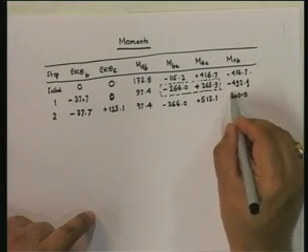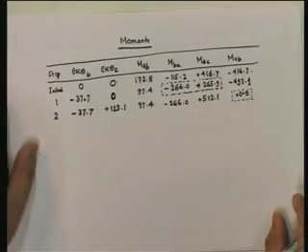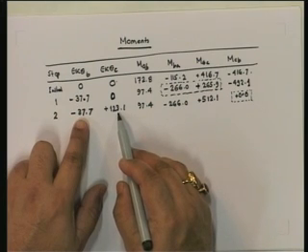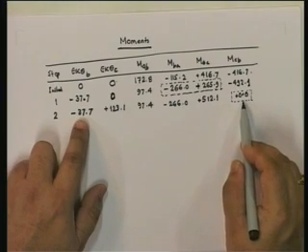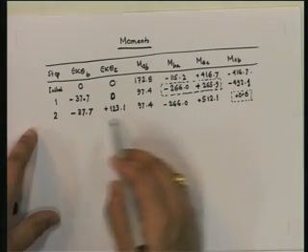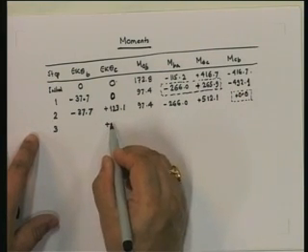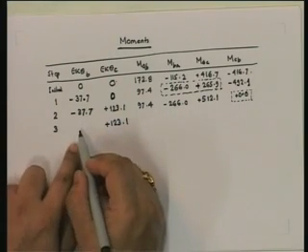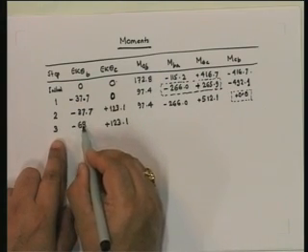What have I done? I have kept theta B and released theta C. As soon as I release theta C, what happens to MCB? It has to be equal to 0. That's what you get. Now the third step is what? I keep theta C clamped at that position and further release theta B. So when I release theta B, I get that equal to minus.